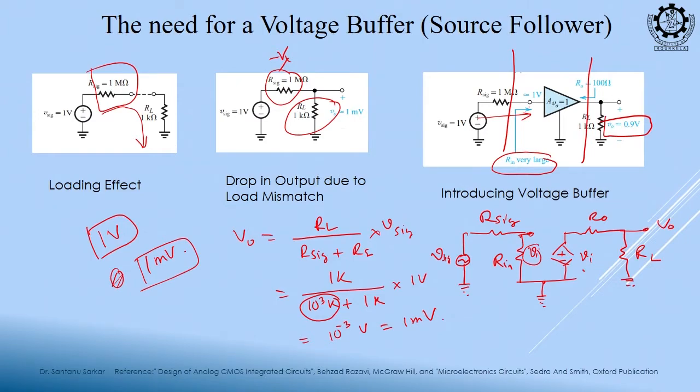So, you understand, when there is an amplifier, if we use the two port network, then it is easier to solve. It just becomes a potential divider, just like this equation, this form. So, try this kind of problem, and you should understand what is the meaning, why this drop happens, and how this buffer can improve it.